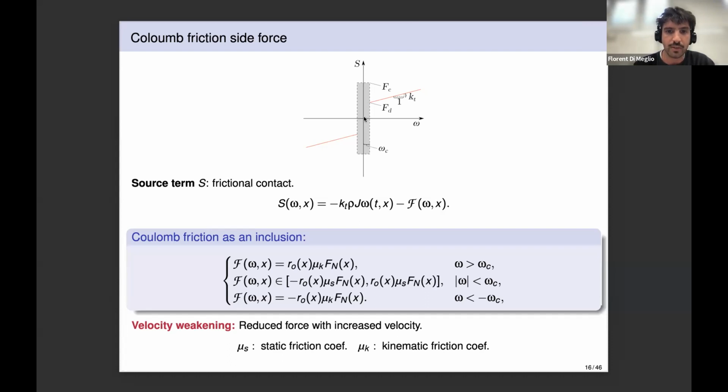Let's say you're at zero torque, so you're right in the middle of that diagram, and then you progressively increase torque. The velocity will remain zero until the torque exceeds the value F_C. And then at that point, the velocity will jump to the red curve as the system starts accelerating and the velocity is not zero anymore. Okay, so this is basically all that diagram says, and the equations below. Like I said, the jump from a zero velocity to a non-zero velocity is assumed to be instantaneous. Usually, you could have a Stribeck curve here in that region, but it's neglected here.